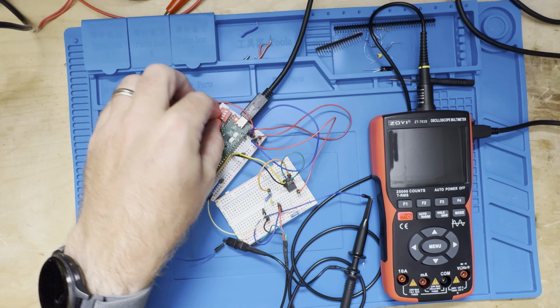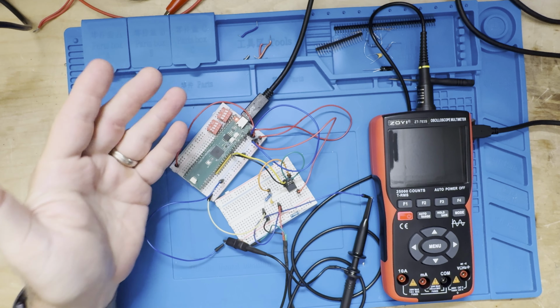Well, the next logical step is we all know that sound is just an analog value varying with time. And obviously, toggling these guys here, I'm not going to be able to do things quickly enough to create actual sound output. We have another problem with sound output in that the output of the DAC chip is between 0 and 3.3 volts, and that doesn't work for audio output. Audio output needs to be AC. It needs to go between 0 and a max and between 0 and a minus max.